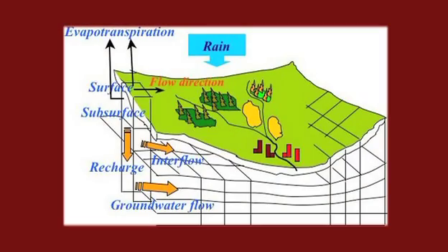Hydrologic models can be lumped, distributed, or quasi-distributed. The lumped models describe temporal variations but cannot describe spatial variations. The distributed models can describe both temporal and spatial variations. A quasi-distributed model such as HMS's modified Clark is a hybrid, that is, a lumped method in a distributed GIS context. The solutions can be analytical or numerical. The models used in practice are numerical in nature, such as HMS.